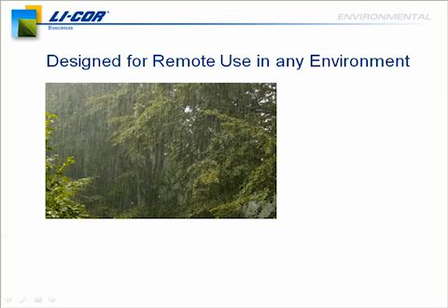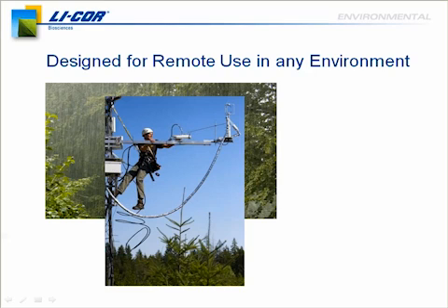Also, the LI-7200 can be mounted on top of the tower at the sampling point of the measurements, and that's an important difference as well, as Dave was talking about, related to long tubing lengths with traditional closed path analyzers and the kind of attenuation and tubing delays and issues that you find there.